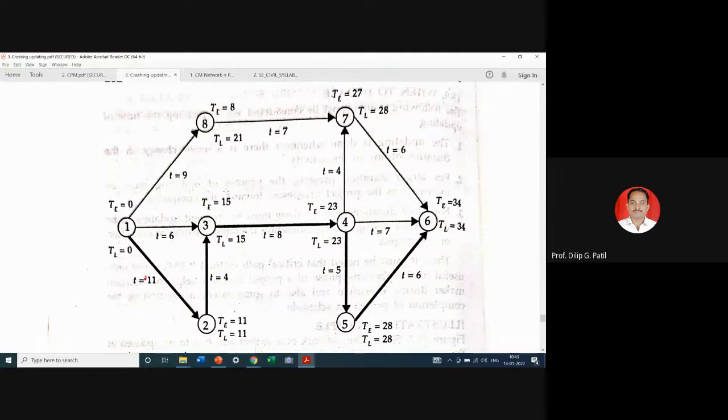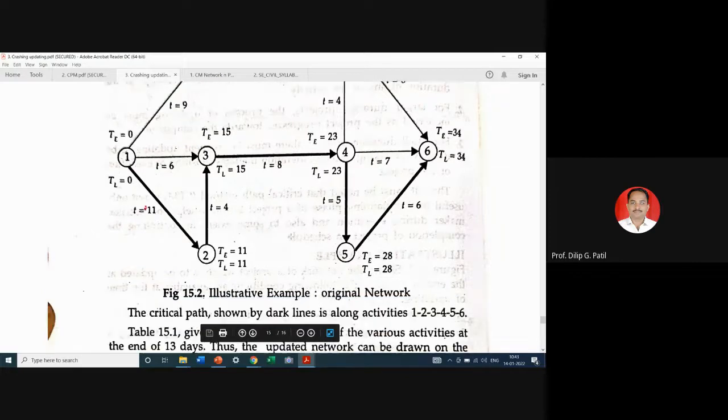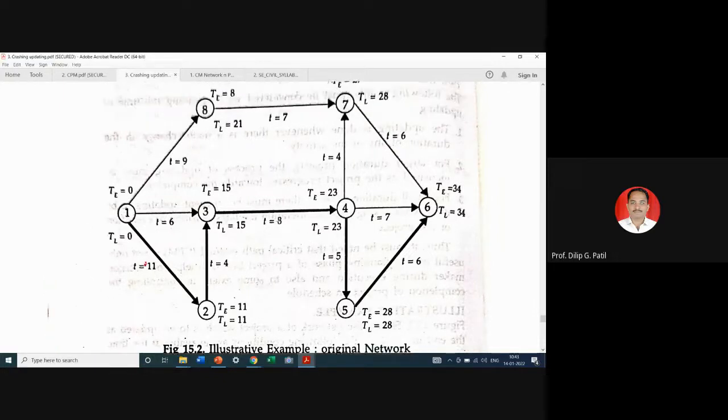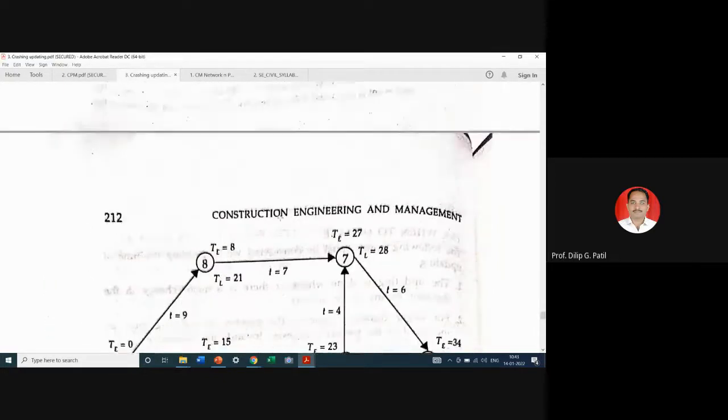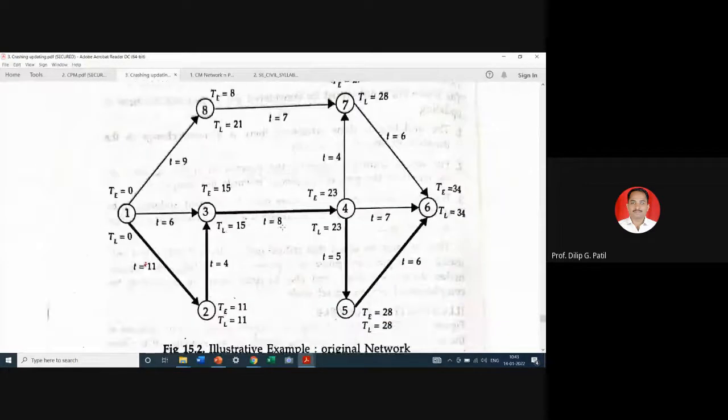Now we need not see how to calculate project duration, earliest event time, latest event time for all events, because this whole process is covered in our CPM lectures. We have to calculate the project duration and also the critical path. Actually here total float needs to be considered, but generally slack is also considered, where the common minimum slack is there.